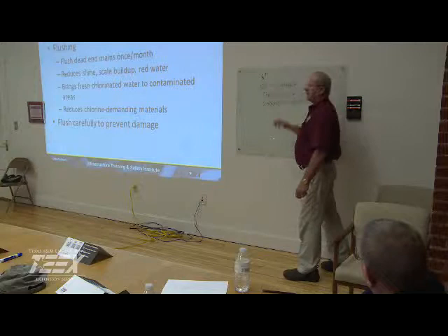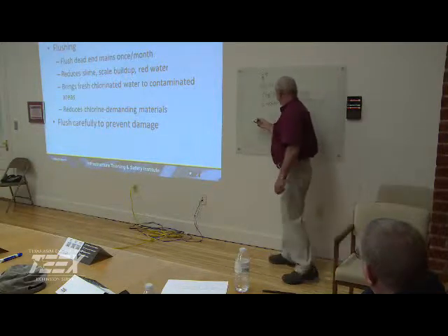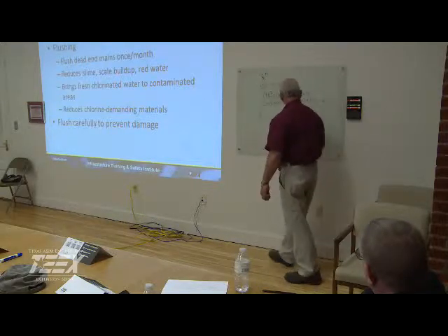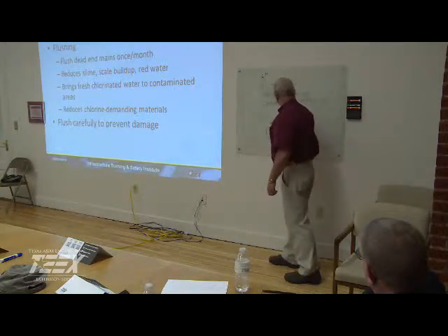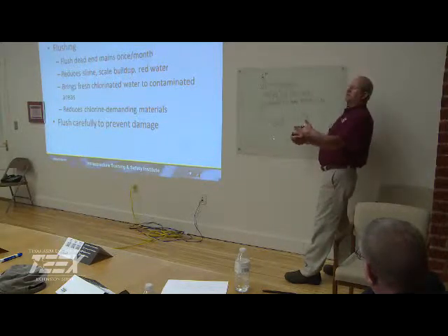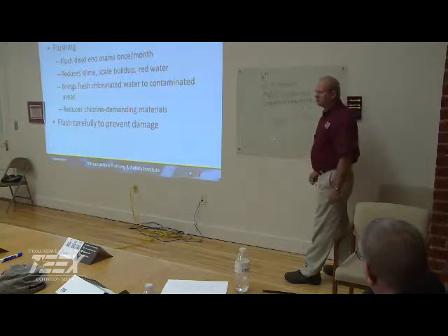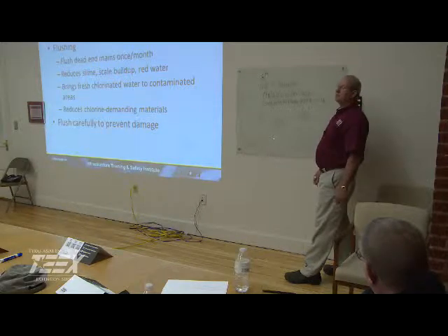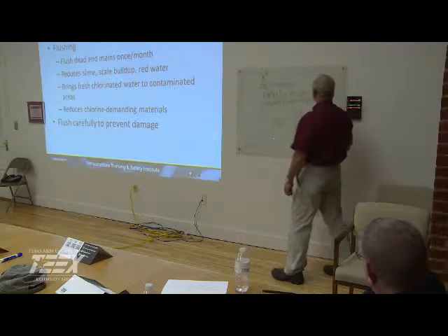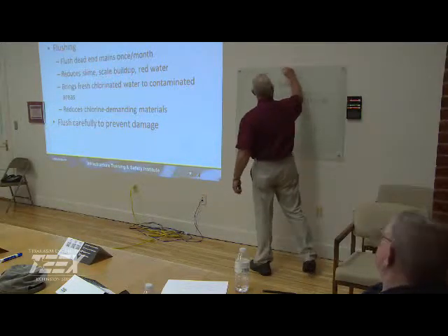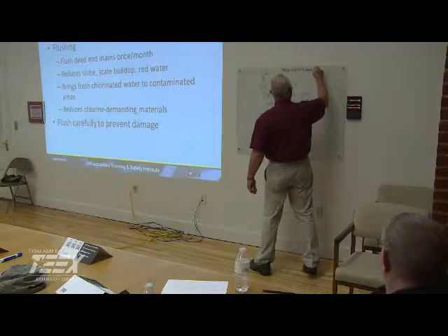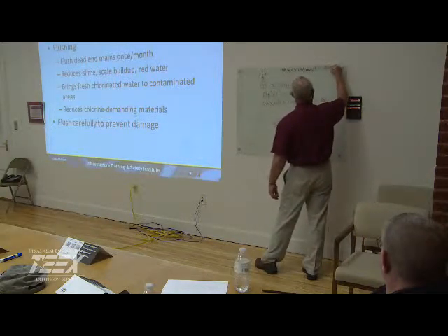So every 100 feet. So let's just say I had that fire hydrant here and a fire hydrant here, and I had a valve here and a valve here. And let's say it's 525 feet. Now we know, let's just say my dosage, we're going to use Texas standards, is 500 parts per million or milligrams per liter of chlorine. So all I do is take my million gallons times my 8.34 times my milligrams per liter equals pounds of HTH.